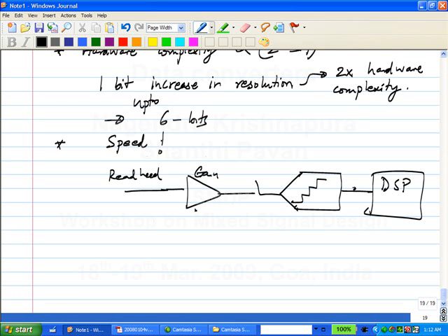Unfortunately, you can see that this is an analog signal, so the signal is probably like this, okay, and this sampling is happening here. It is very likely that, for example, you're sampling at the wrong instant. So let's say this is a 1 0 1 0 stream, right? Ideally, where do you think we should sample? You should sample at the center of the bit, correct? But in the beginning you will not know where to sample, so you just keep sampling, and let's say you landed up with sampling here, okay. If you just look at those samples, you will think that the data written is all zeros, right? Or you can't make any sense of the input at all because it always seems to be 0.